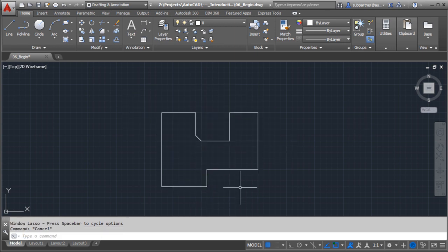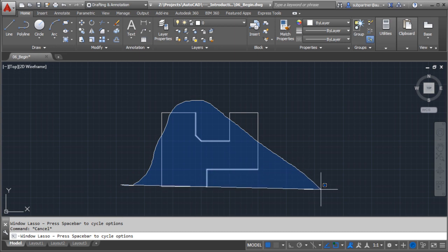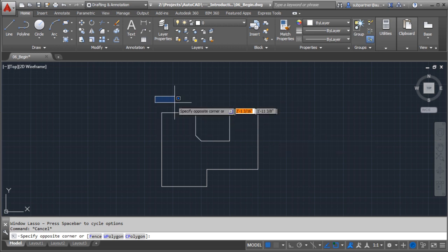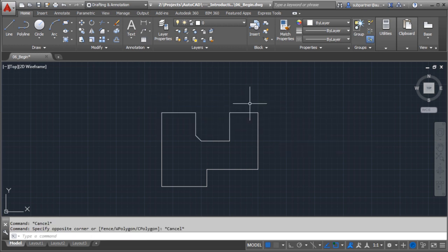Easy as that. Now, that same behavior applies when you're going the other direction. So you can see the color of that window. I know that selecting this way, only the elements that are totally inside that window are going to be selected. There's other elements that are chopped off. Those won't be. Perfect. You can see these lines are selected. So there's two ways, left and right, keep in mind. But there's also another way within that, and that's holding down the left click button and just simply clicking it to get the square.